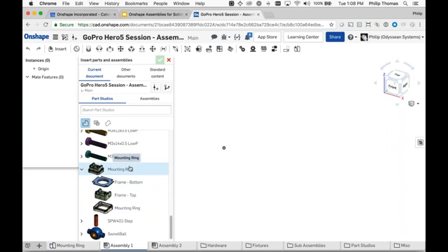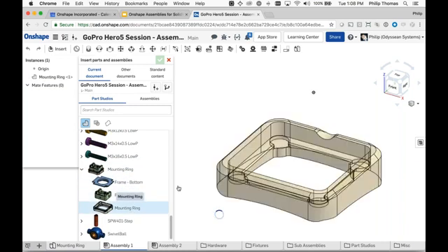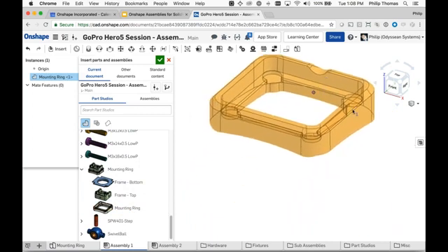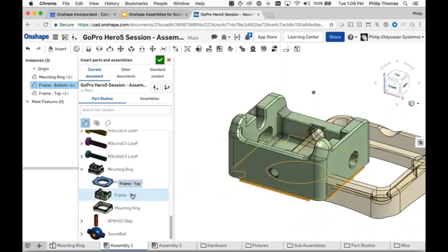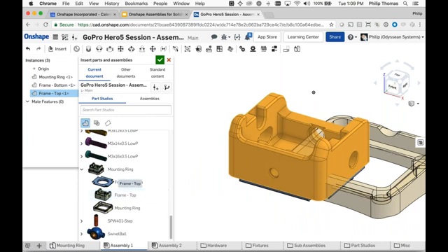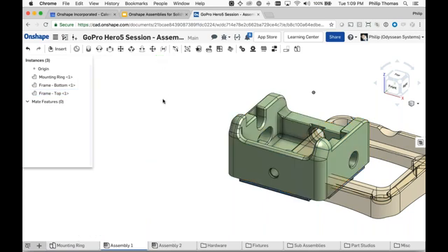The ability to insert an entire part studio is a convenience. There is actually no difference between inserting the entire part studio and inserting these 3 individual parts, meaning it is not parametric. If I add another component to the part studio, it does not appear in the assembly. The mechanism for inserting is basically clicking on the part and then dragging it to a location in space and dropping it. If I don't specify a location in space, the components will appear in the same spatial relationship to the assembly origin as the parts were in the part studio.